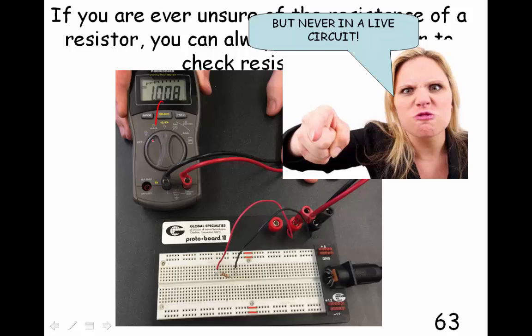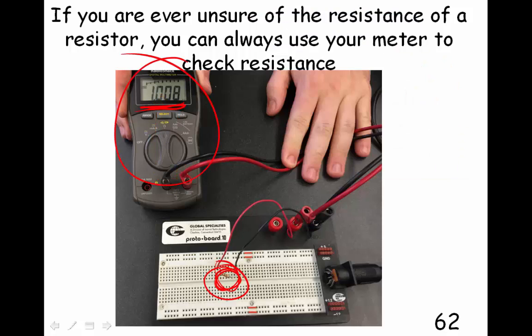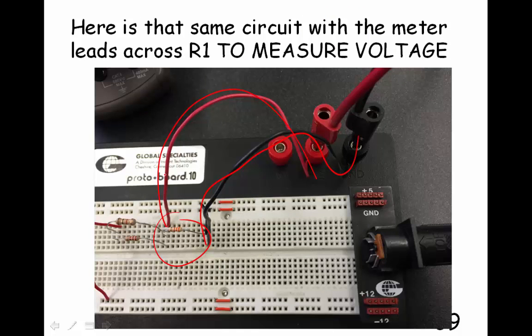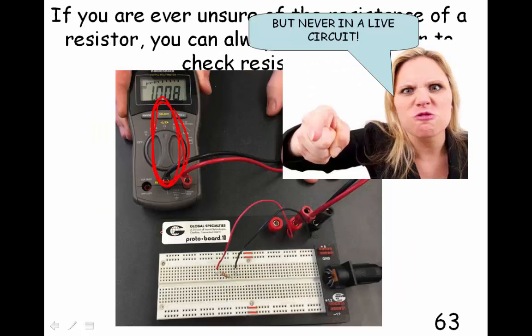Never turn your meter onto ohms when you have the circuit live. Like, let's see, like this circuit right here is hooked to a power source. We couldn't just try to measure the resistance of that resistor with our ohm meter because there's already current going through there. And remember, our ohm meter sends its own current through it, and it'll start fighting with our power supply, and they don't like it.